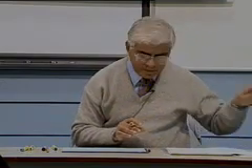Yes, please. Sir, I have a question on the power we just calculated. In the numerator we had 1/4, but the lower sideband you said isn't required, so should we just have half? No, we are only talking about the modulation that we are working with right now. If we remove the lower sideband or the upper sideband, we are working with a different kind of modulation, which we still have to discuss.